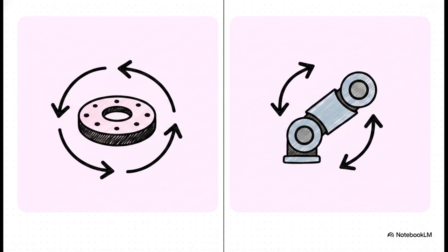But the arm rotation, omega-2, is lifting up and down at 2 radians per second around a local x-axis that is turning with the base. We call this local rotation omega xyz, and it's equal to 2I. We absolutely must keep these completely distinct.